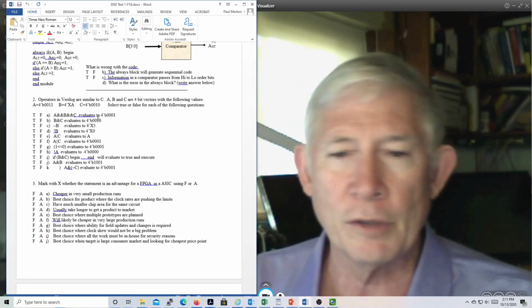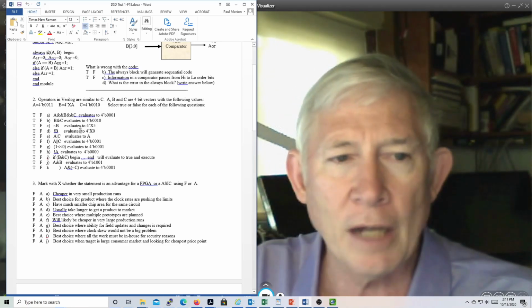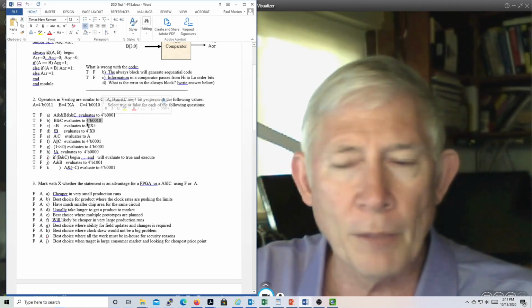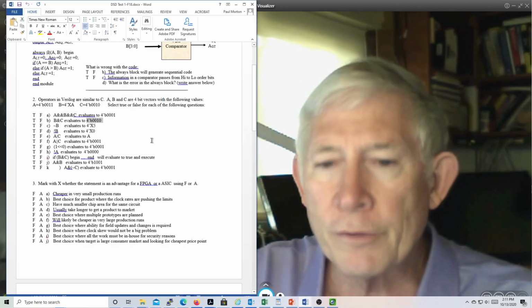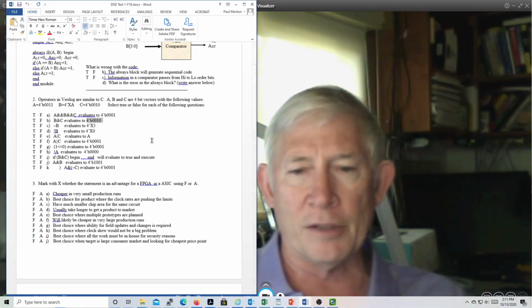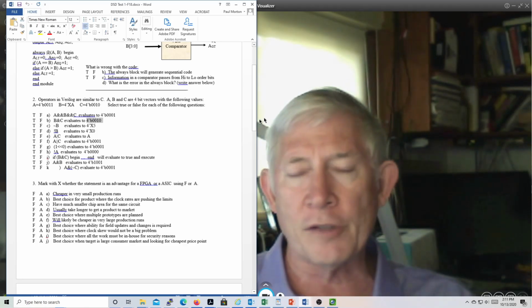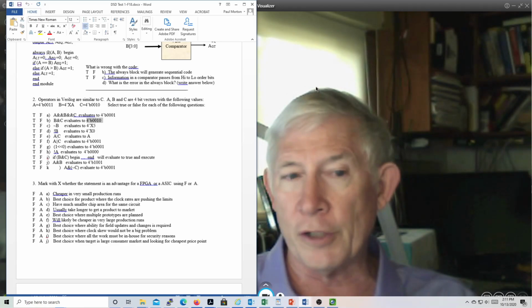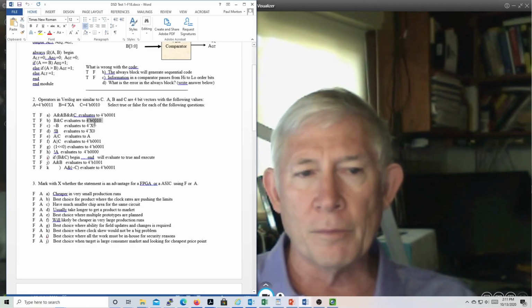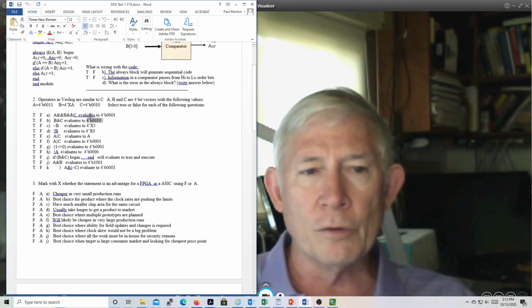We did a whole lecture on all the exigencies involved in creating constants. This is how you do constants in Verilog. You put a number, and that's the number of bits. It's not the number of digits. So if you do hex, you do 4'h. That doesn't mean you get 4 hex digits. It's still 4 bits. The first number is always the number of bits, and if you don't put it, it's assumed to be 32. Then you put a tick, and then you put the radix: B for binary, H for hex, D for decimal, O for octal. And then you type in your number.